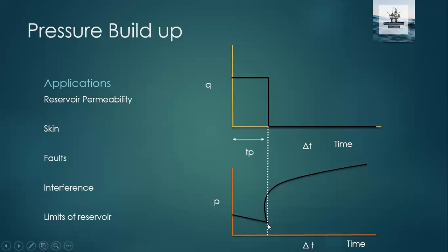During shut-in condition, or closed condition, pressure starts to rise up. It will rise until it reaches maximum pressure. That maximum pressure is equivalent to reservoir pressure, or initial pressure. So the pressure where it had declined before shut-in, it will start from that, and until it reaches the maximum pressure, the pressure keeps rising. This is exactly the process of conducting a pressure buildup test. While building up, you can observe that the flow rate will be zero.